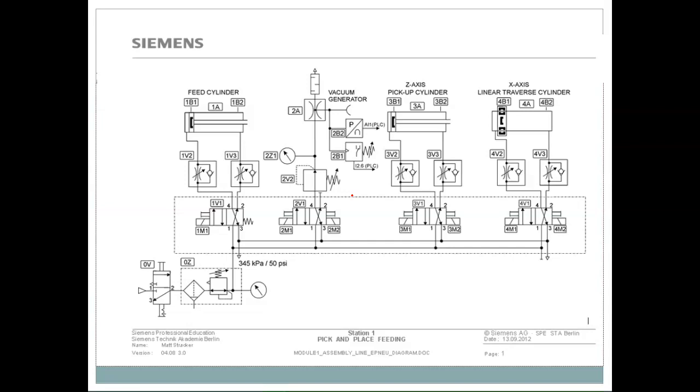And it would work the same way the other way. If I put pressure on this line and move this guy out, he would move out very slowly, because while pressure is being applied back here, the pressure up here is being let out very slowly. It takes a very long time for that pressure to leave. Does that make sense?